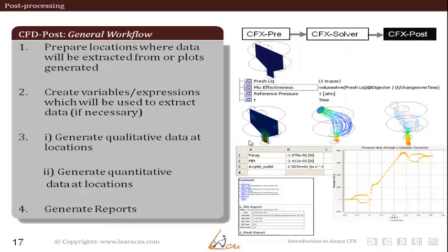Now we will see what is the general workflow when you use CFD Post. The general workflow that is followed is first you start with CFX Pre, then go to CFX Solver, and then we go to CFX Post or CFD Post. So let us take an example of this particular case.